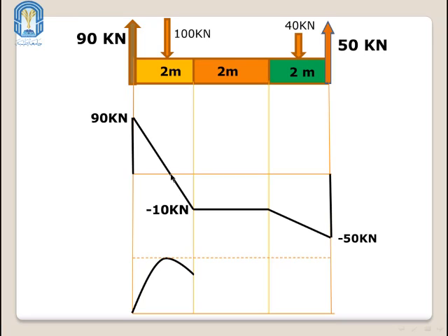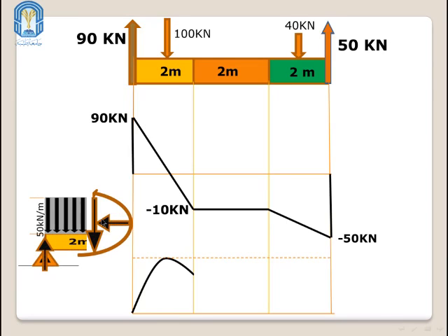We will take a cut from this part because the shear force here equals 0. If we take it, we will go like this, and we have here, almost here, a distributed force, and we will cut it from here, and it will be like this, as you see here. We have a new base x, but the same height, and we will determine our sigma F of y, because we don't need our moment or our sigma F of x, we only use sigma F of y, and it will be like this.